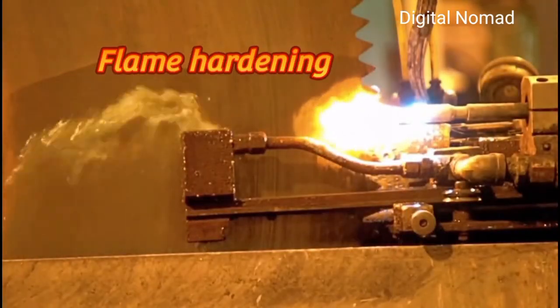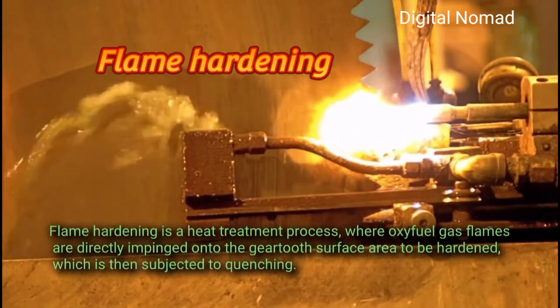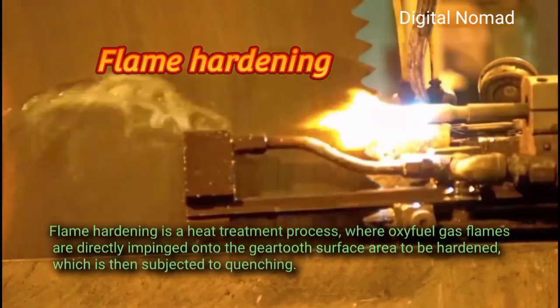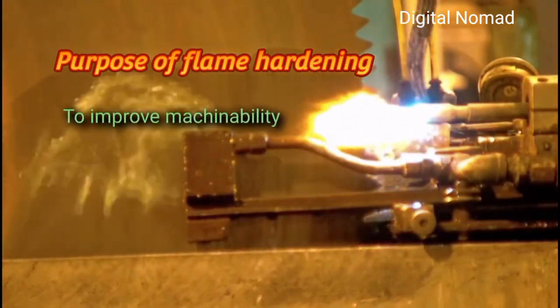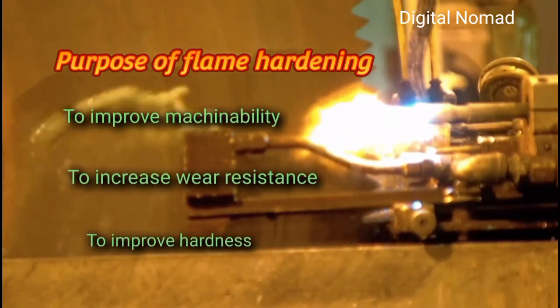Flame hardening. Flame hardening is a heat treatment process where oxyfuel gas flames are directly impinged onto the gear tooth surface area to be hardened, which is then subjected to quenching. Purpose of flame hardening: to improve machinability, to increase wear resistance, to improve hardness.